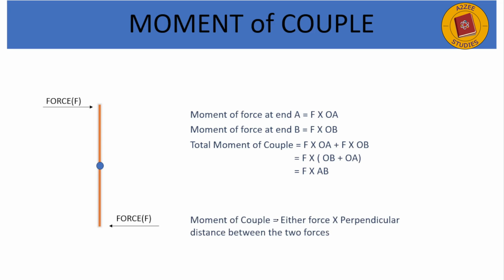Now what is the moment of couple? Moment of couple is force applied multiplied by the perpendicular distance between the application of the two forces, this distance. If we take it as d, the moment of couple is only one force. It is not that F plus F into d, it is only F into d.